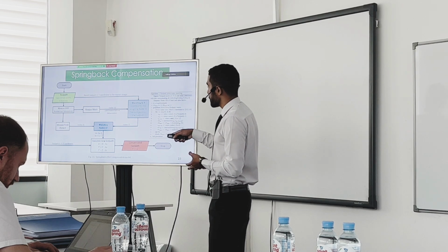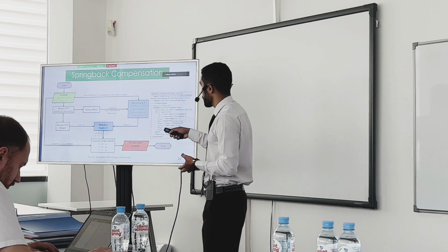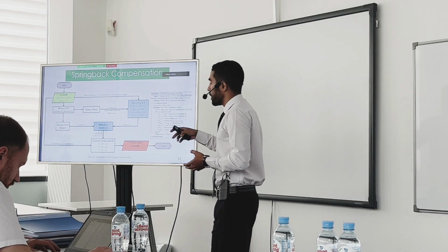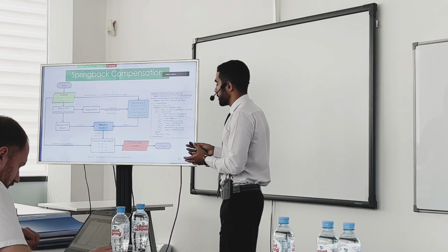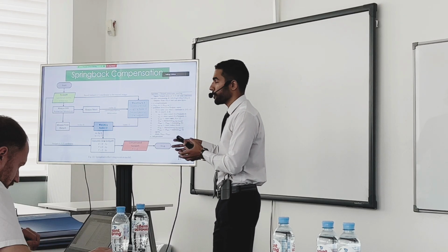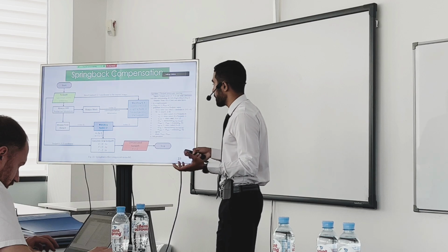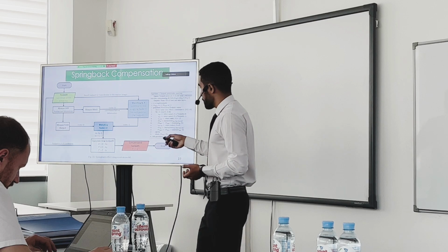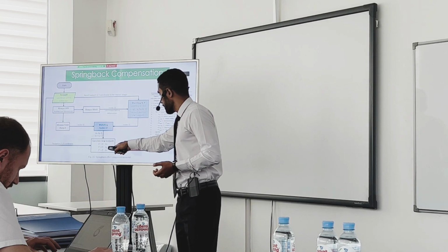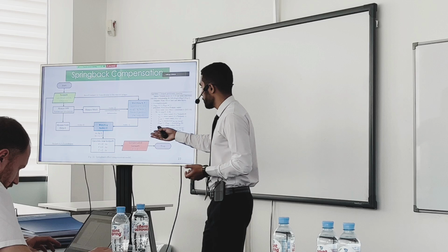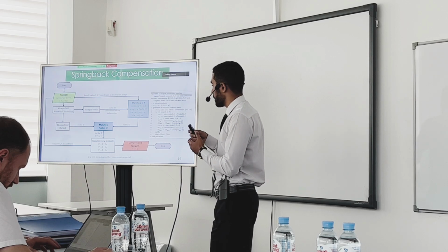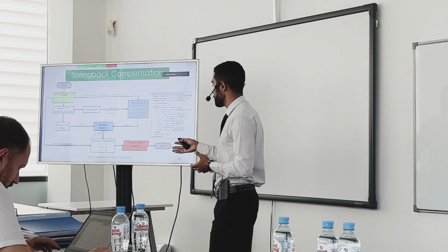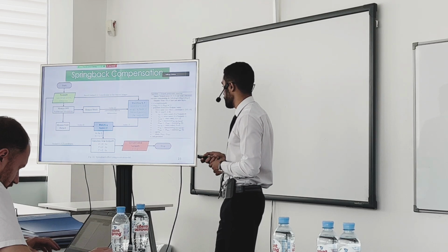The key point in this flow chart is these two blue boxes, because basically the idea is I'm getting the data before the deformation, and I'm tracking the nodes after the deformation to get the new toolpath. The new toolpath can be calculated finally, which here I refer to as x prime, y prime, z prime, just compensating for the deviations of these nodes from the desired toolpath, I mean the original toolpath.